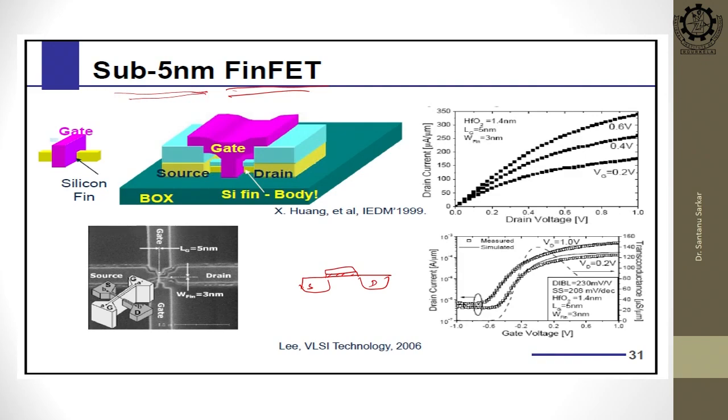If you look at all the smaller dimensions, you will see that mostly all of them use this new technology, the FinFET. Otherwise, in MOSFET, if you go below, it is very difficult to have the desired characteristics. FinFET has certain advantages here; its subthreshold leakage is also improved. There is still a lot of research going on, but it is stable.